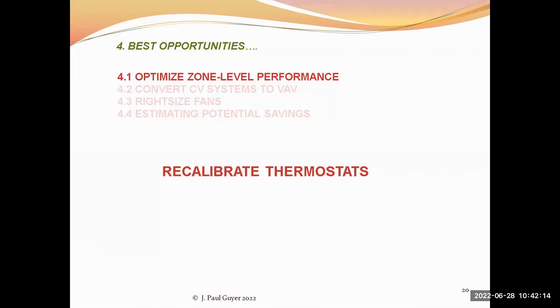Though the thermostat calibration should be checked if a complaint arises, a comfort complaint by occupants, but it's also preferable if you just write this into your routine operations and maintenance procedures for the building, and check the calibration and recalibrate the thermostats in the spaces.